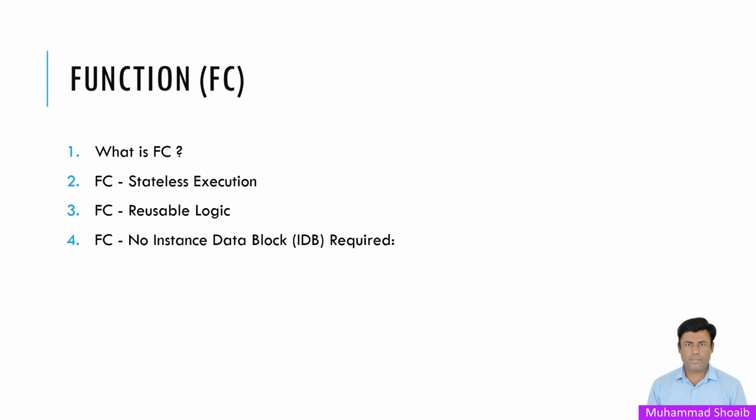Unlike function blocks (FBs), FCs do not need an IDB, an instance data block, since they do not store any data across a scan. This makes them lightweight and efficient.